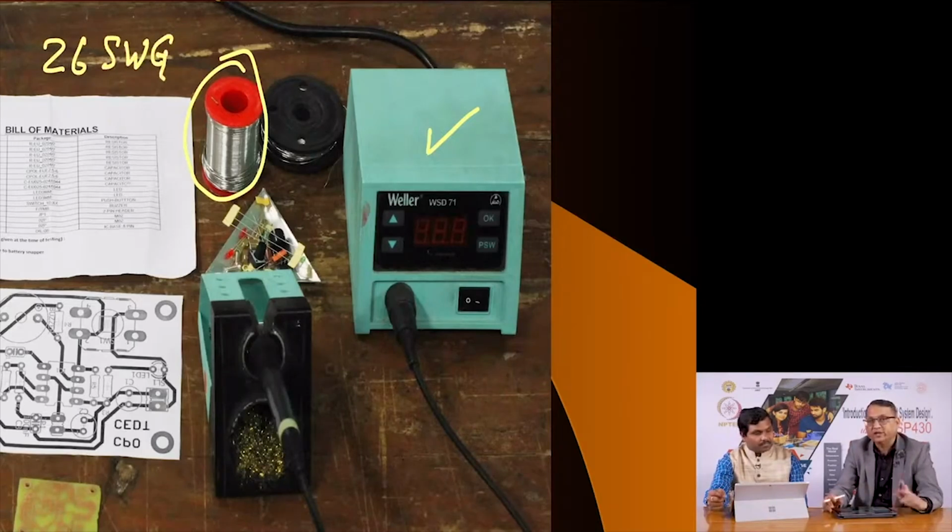By the way, the solder wire is not solid, it is hollow, it contains flux, and the proof of that is when you melt a solder wire on a solder iron or a solder station, you will see vapors, and those vapors are because of the chemical flux. This chemical flux helps to cleanse the surface. When you are soldering any electronic component, it cleanses at a nano micro level, which you cannot clean otherwise.